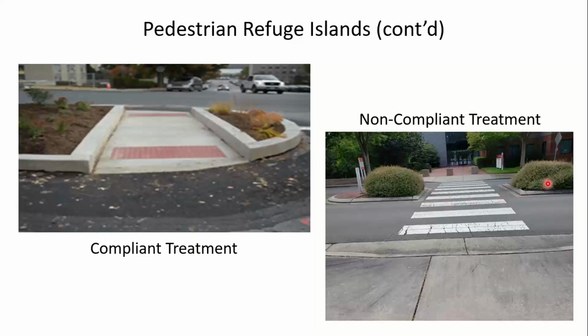But over the years, you can see they've grown rather high, and now I consider these to be sight distance obstructions. Again, you could have someone in a wheelchair or a child trying to cross here, and motorists would not be able to see them due to the size of that shrubbery. So not to discourage the shrubbery, but there is a need, of course, to trim it and prune it and maintain it so it doesn't grow to become a visibility obstruction.